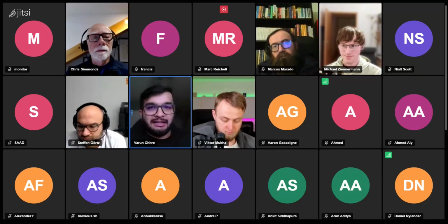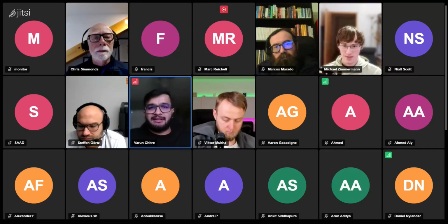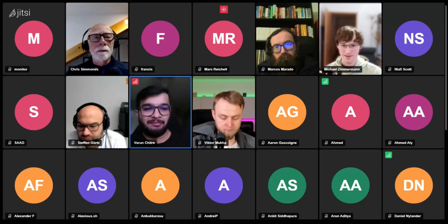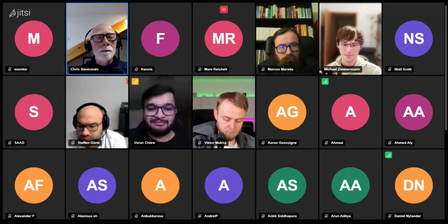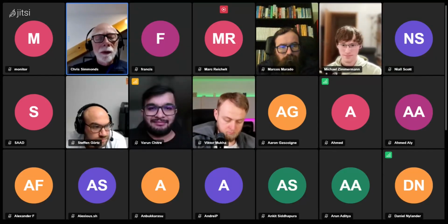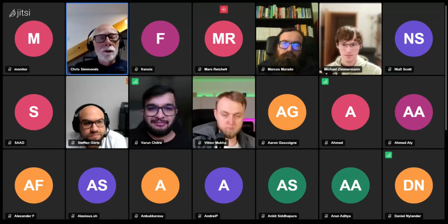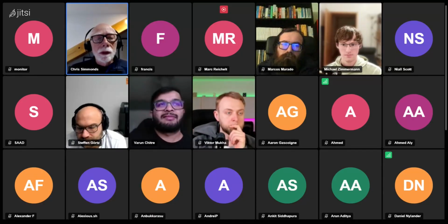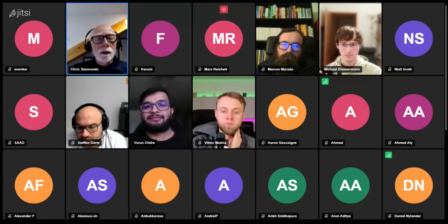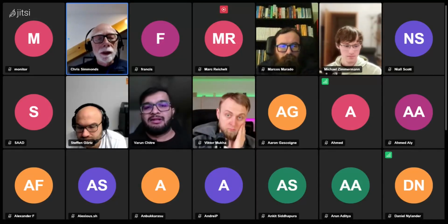Got it. Thanks. Yeah, the CAN bus controller definitely intrigued me because it's mostly present in infotainment systems in cars. If I can just butt in there for a moment: in my experience, the USB CAN bus controllers are great for debugging and proof of concept and such. I'm not so sure they would be used in production, but I could be wrong. I've only ever used them for playing around and doing quick demos.